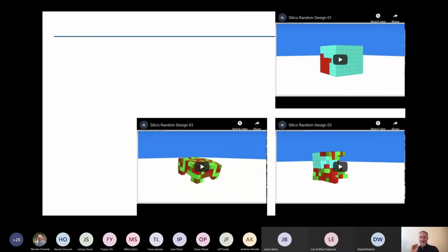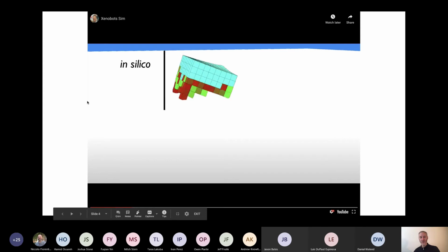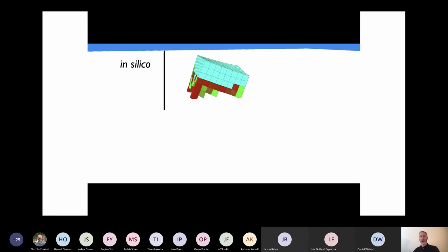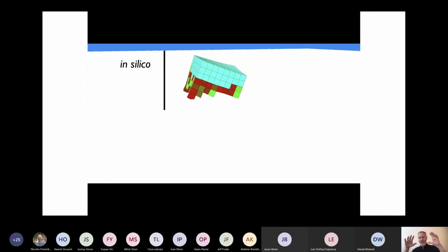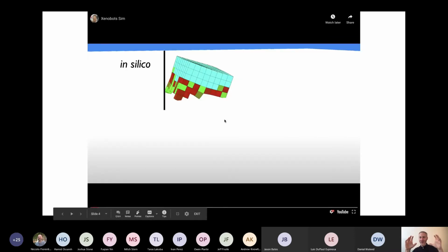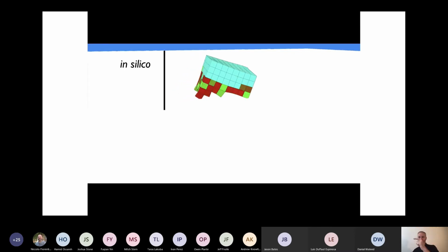However, despite the difficulty of this task, if you repeat this evolutionary algorithm for hundreds or thousands of generations, you get something like this. This was the best design the evolutionary algorithm was able to produce in simulation. You can see that it places heart muscle tissue on the ventral or bottom surface of this little xenobot, and the passive skin cell on the dorsal or top surface is somehow damping out our assumptions about non-entrainment, the random phase offset. So in a way, the distribution of tissue here and the 3D shape of the xenobot itself is collectively de-randomizing the random action of parts of the body. So you get a more or less straight line of travel from left to right.